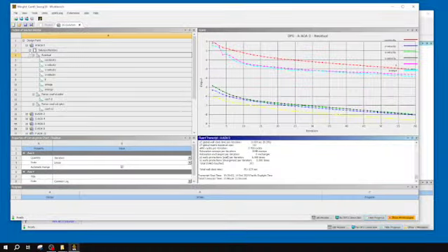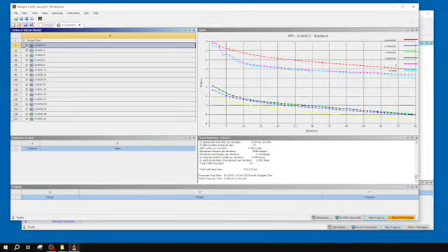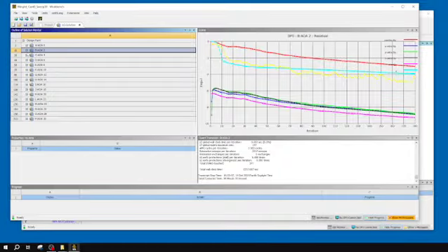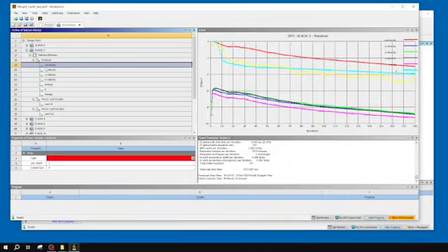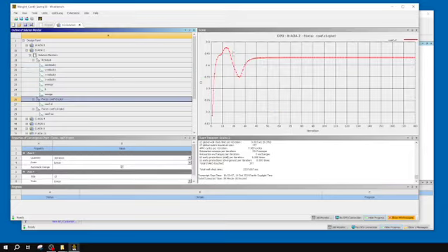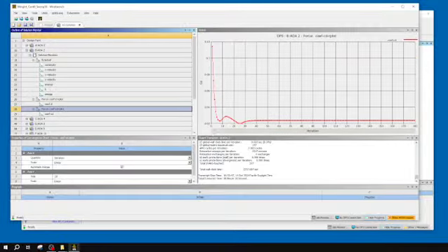If I look over, let's say at my 2 degrees, we can see, again, we had convergence, but it took till about 180 for this one to converge. And you can see how convergence plays out in your lift and drag. You start with some of this variability, and then it finds an answer that it likes, and it stays with that.